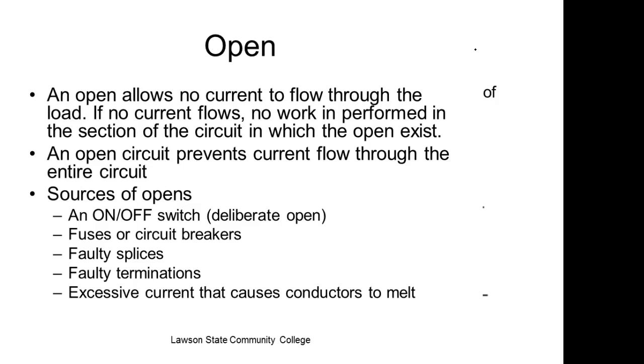Okay, sources of opens, of course, we have open switches, fuses, circuit breakers, faulty splices, and tension breaks where we ran conductors and didn't allow for expansion and contraction. Just about everything we've got gets bigger, right? You understand? Rule of thumb in networking is to leave at least one loop.